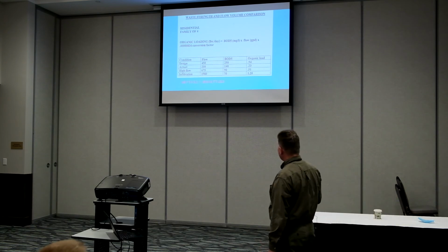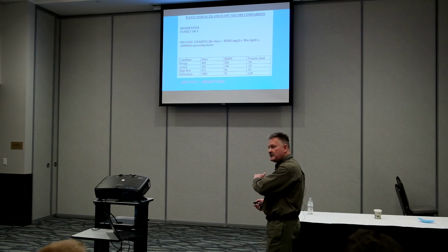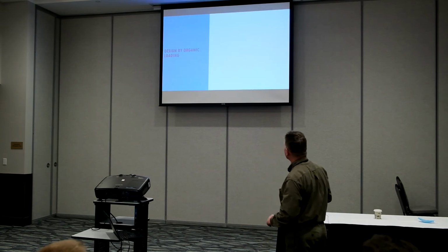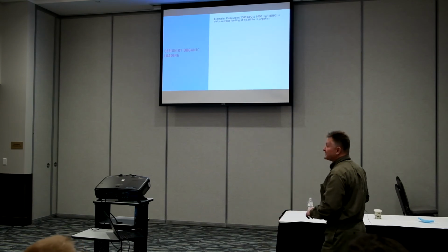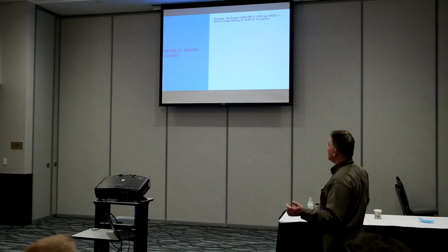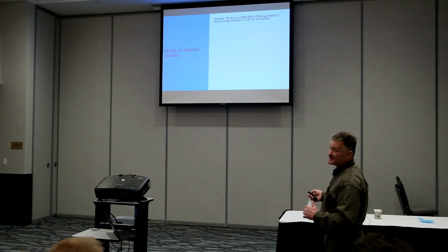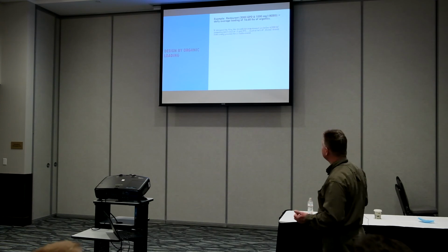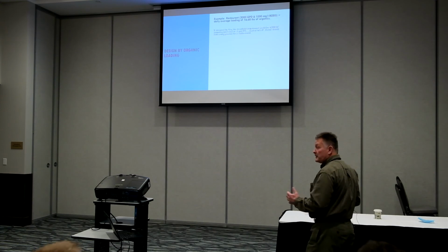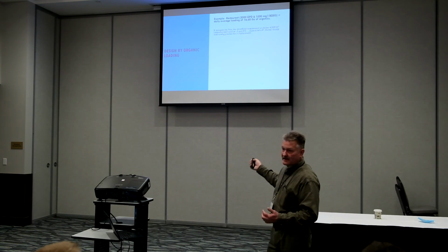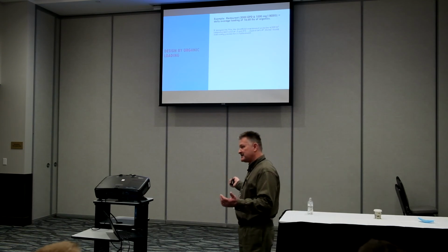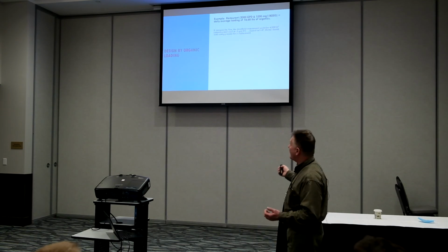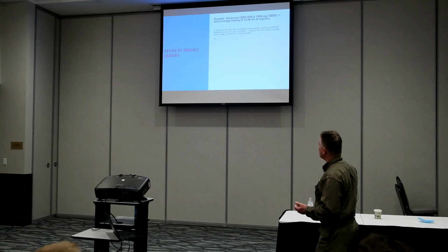And so what if we apply that to a commercial application? Say we have a restaurant, 2,000 gallons a day, 1,000 milligrams per liter. That comes out to over 16 pounds of organics that we have to treat through that system. So if we design by hydraulics, medium sand, that's 1/2 gallon per square foot, we need a field to be 4,000 square feet.